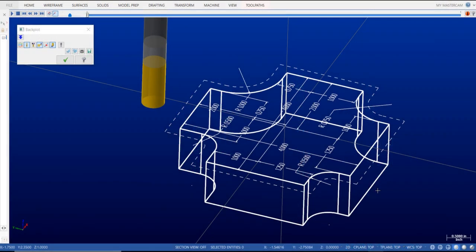Alright, so far we've learned that when we create a tool path for the outside of a part, we're always going to pick it in a clockwise direction, and therefore the tool will always be climbing, and that's what the machine likes, climb cutting. When we add cutter compensation for an outside contour, we're going to be adding line left cutter compensation, and that's done with a G41.